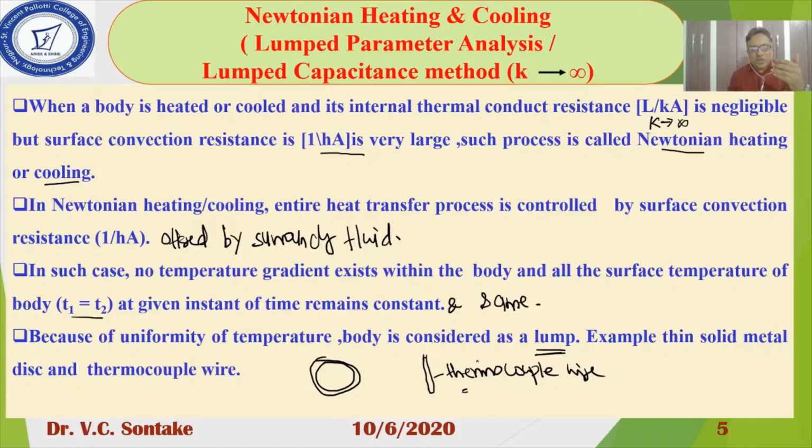The temperature of either this thin solid disk or thermocouple wire is assumed to be constant everywhere by virtue of zero or negligible thermal resistance. And under such condition, the entire process of heating or cooling is governed by the surface convection resistance of the surroundings.